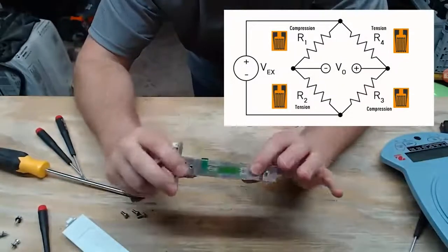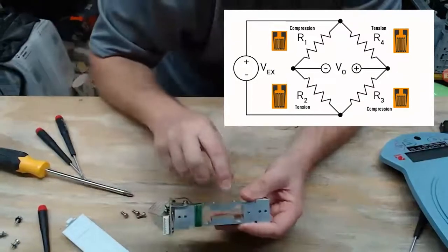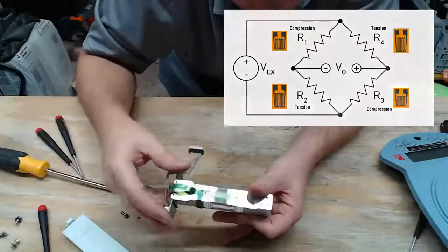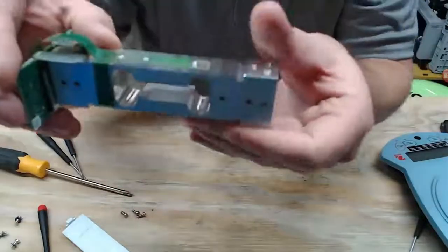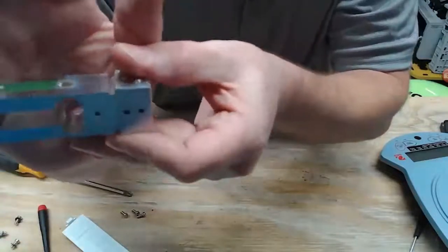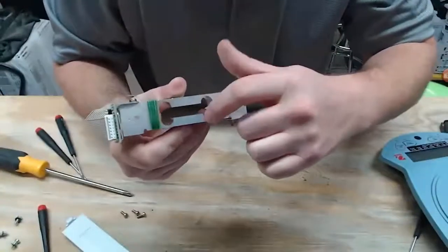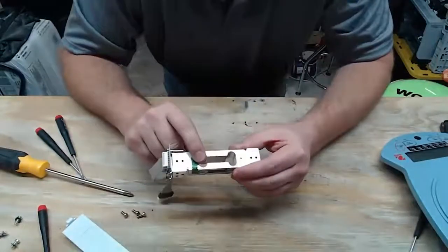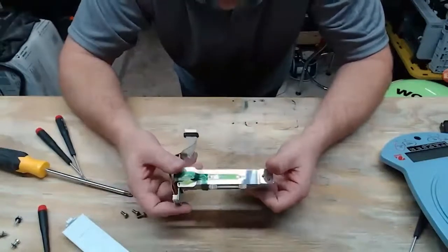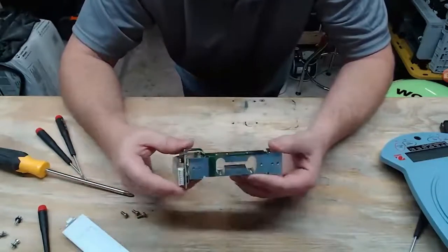Now, these load cells use a circuit called a Wheatstone bridge. What you're doing is balancing out adjacent corners for expansion and compression. Let's take a look up here. Camera picks it up. Come on. There are tiny little grinding marks inside right here, because what they did is they removed some material here and here to bring it within its calibrated value. That's really interesting. It's a sloppy way of doing it, but that's definitely a sure way.